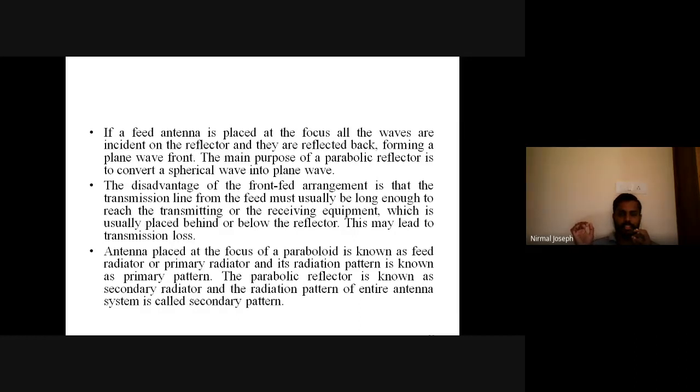Okay, that usually leads to transmission loss, because that much length is there for the transmission antenna or transmission element or feed element. Due to that, some transmission loss will be there. From the source or the transmitting element, the signals have to reach up to that particular point, the focal point of the parabola. During that, transmission loss can happen.